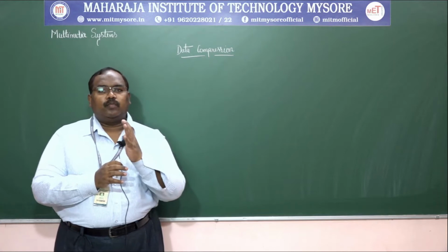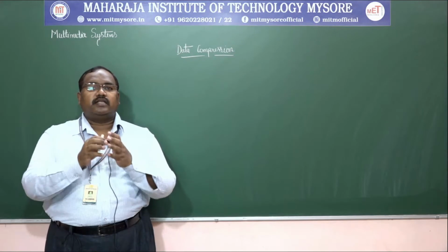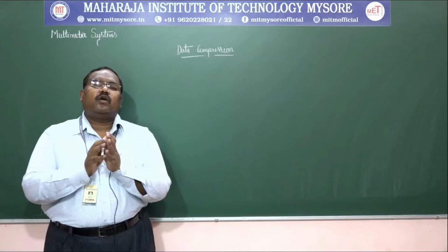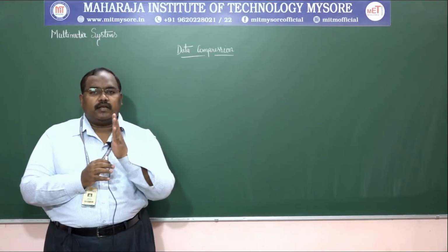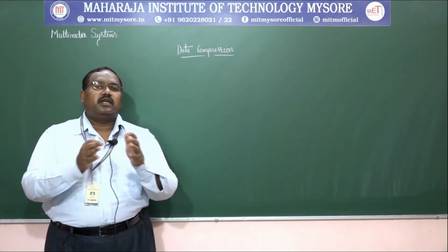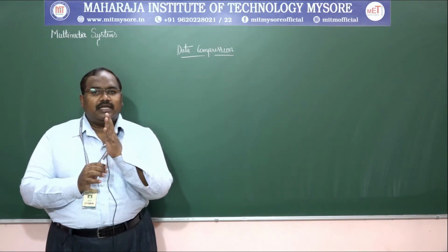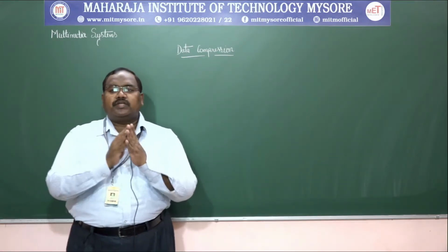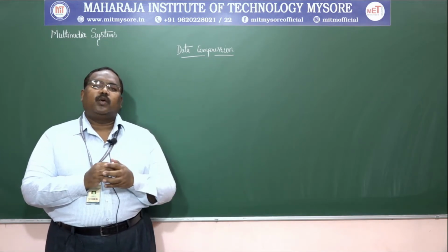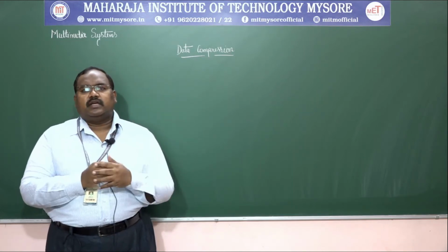We have seen the two picture video formats, that is CIF and QCIF, and we extended our discussion with respect to H261 compression, which includes a combination of various techniques like interpicture prediction, transformation coding and motion vectors. We have seen this in detail, and also discussed the detailed design of H261 compression with respect to prediction, block transformation, quantization and entropy coding. And we have seen the advantages and disadvantages of this compression technique.